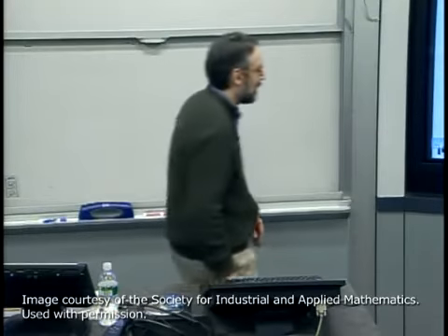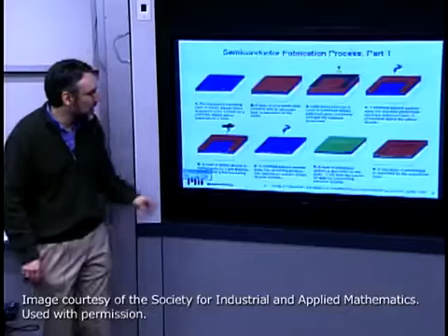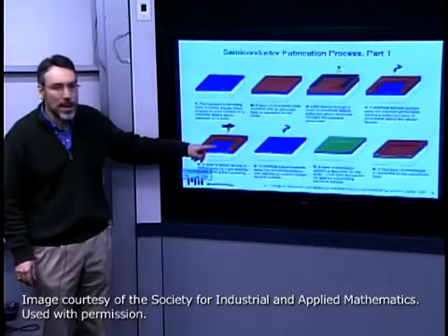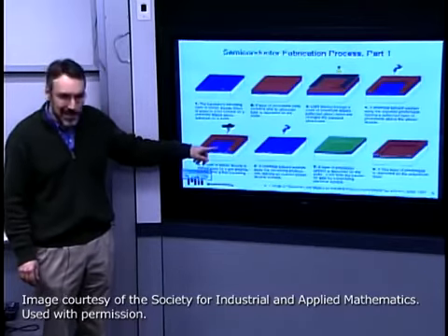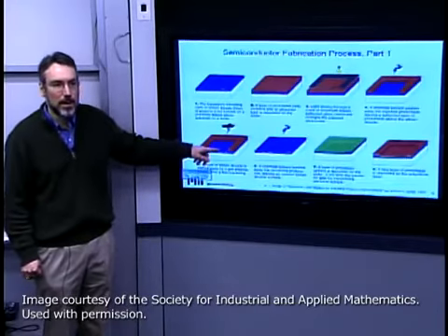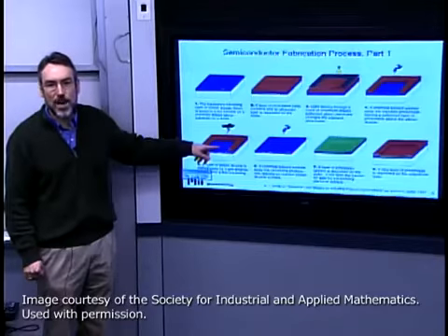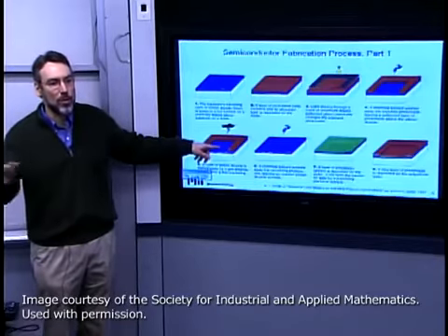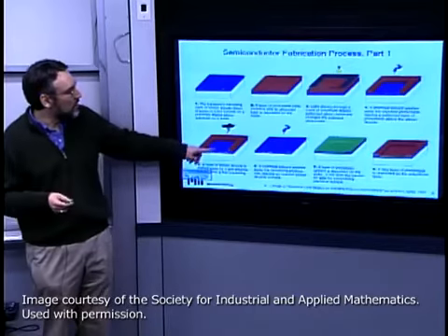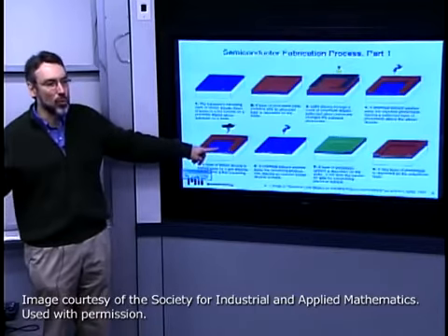At present, at least, and there are some additional reasons why one wouldn't want to do it, but at present, we don't have the observability to be able to know when we're within 100 angstroms. Second, there's no way you could be that uniform across the whole wafer. I mean, what if on one part of the wafer, instead of 5,000 angstroms, it was 5,001 angstroms?